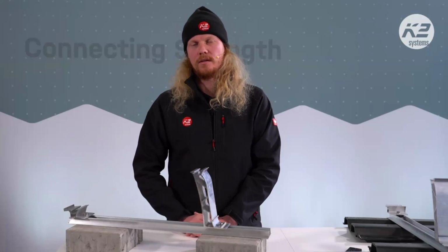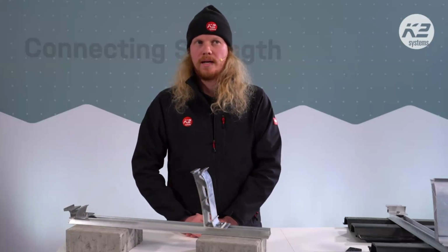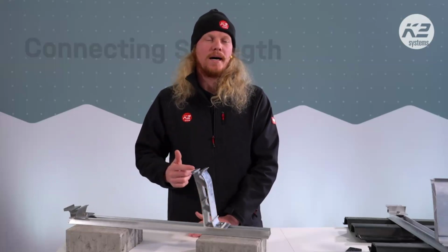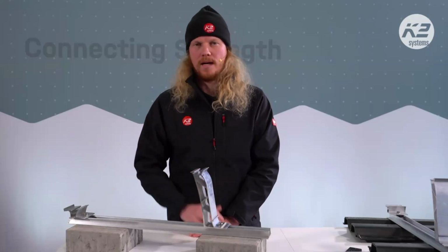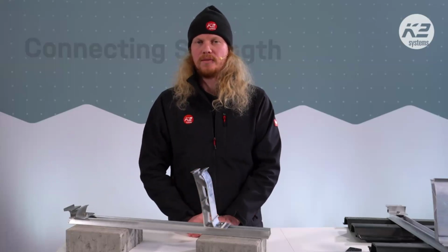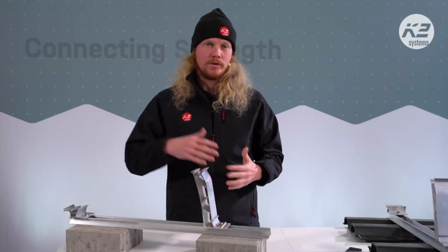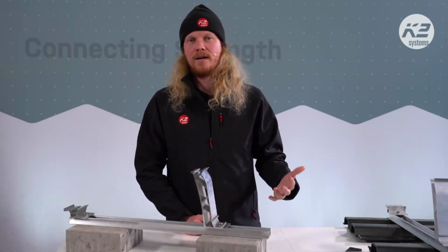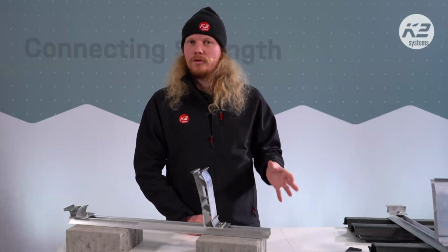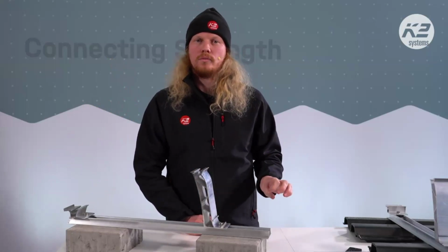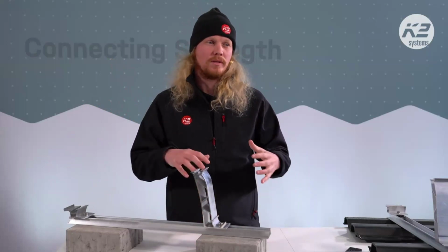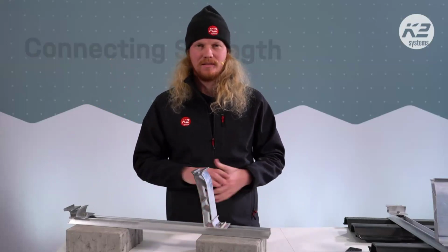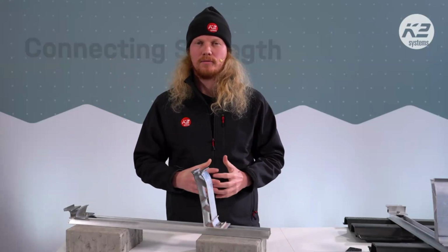It's actually shown in kilonewtons per square meter, but you can convert that quite easily to kilograms per square meter or vice versa. If it's too high, so maybe in the example I had before, you've got 30 or 35 and you need a 25, in situations like this you might have to use an anchoring system. That's not really for this setup here, but just a standard flat roof setup.